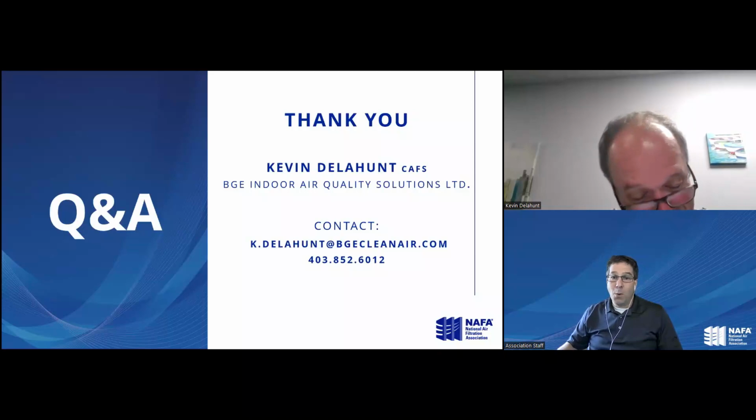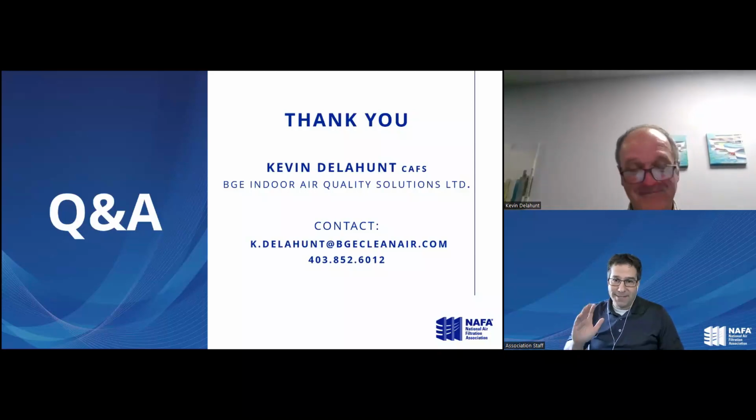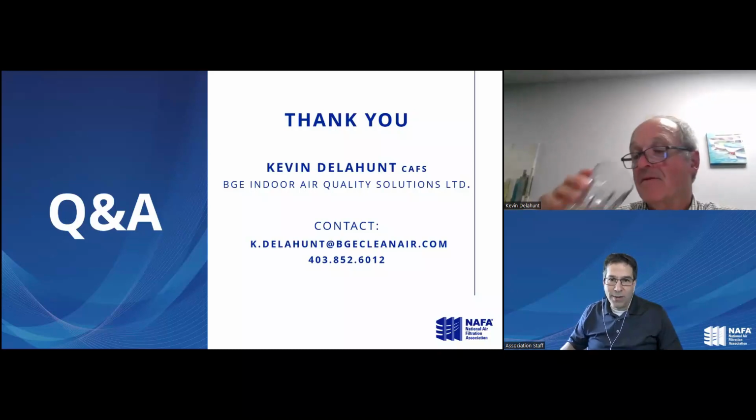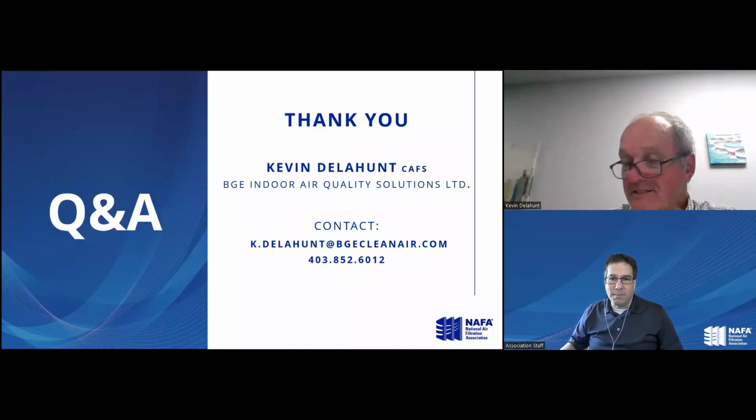Long-winded, but yeah. Well, and maybe just again, as a layman like myself, we're all our own technicians for the most part, right? So like you said, ask yourself the question: is all the air going through the filter? Does it make sense to have a MERV 13 if the air is bypassing? That turns the MERV 13 back into a MERV 8, and you haven't accomplished anything. But a MERV 11, we feel that most systems could handle without any modifications to their system. So again, work your way up.